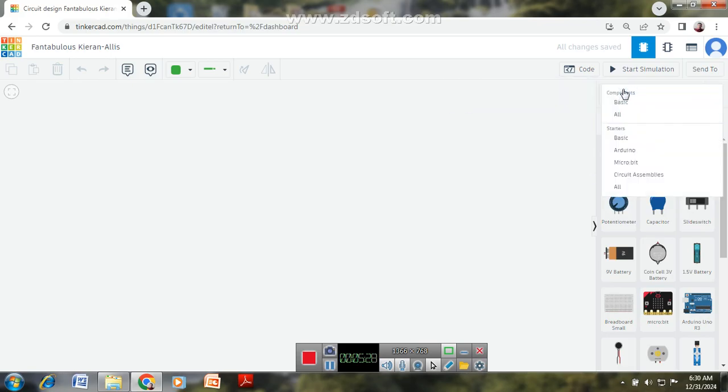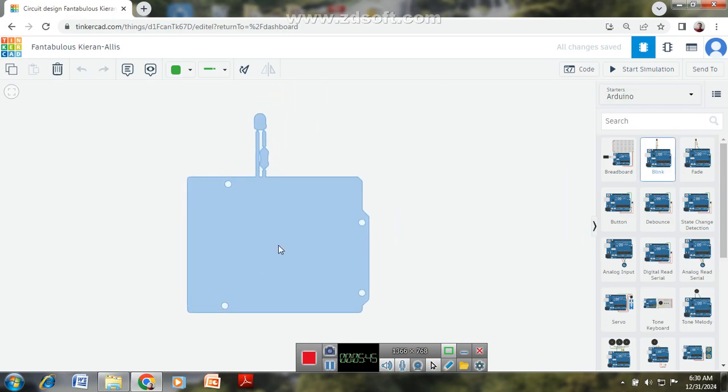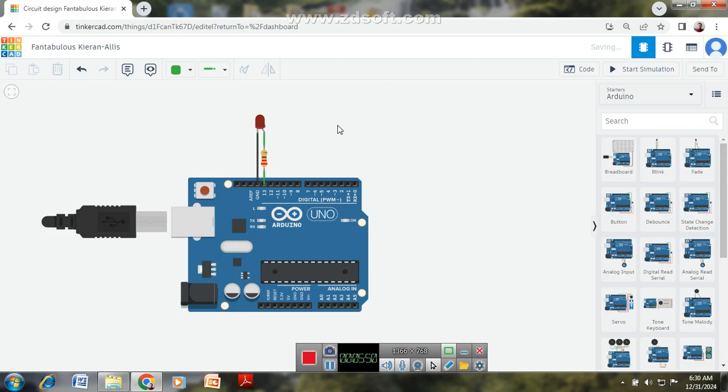So you have to click the Arduino now. It is automatically a pick and place component. So you all should be able to do this particular experiment easily. So you have to click this blink. Just click it and place it in the schematic part. What connection is going to be used here?